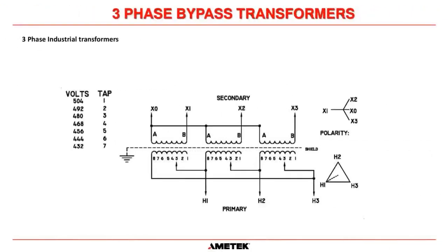Here's a three-phase transformer, 480 to typically 120/208. And again, we've got taps on there to select the proper voltage. Oftentimes these transformers go in and nobody bothers to look at the taps it's set on, and maybe they're set up because the 480 bus doesn't run 480 volts.